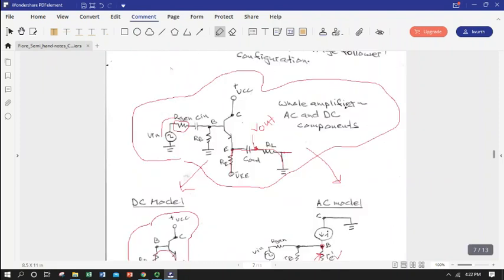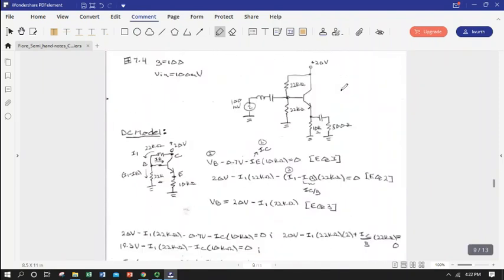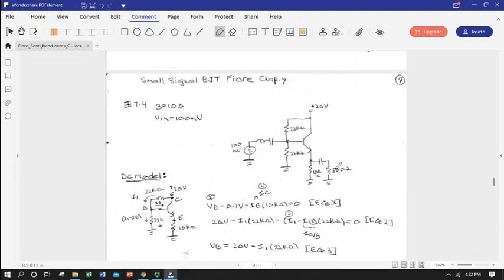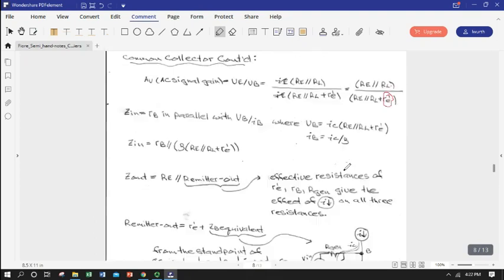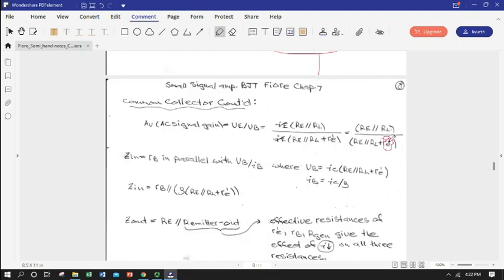So for example, let's just scroll down. We'll jump ahead to a typical example. So we have 500 ohms and 10K. So we put those in parallel, and the parallel combo is going to be something a little under 500 ohms. So we're comparing, say, 50 ohms to 500 ohms. Given the typical value for R sub E, it's just going to go away, which is effectively going to leave us with the R E R L parallel combo in the numerator and the denominator, which will cancel out and create the big 1 mathematically.